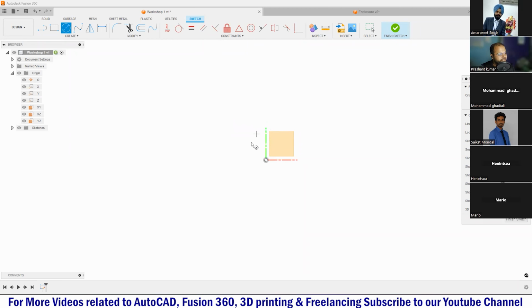So let's say I'm creating a circle. I will just select the center point of the circle and drag outside like this. Whenever I am dragging, there is a dynamic box. You can see that inside this dynamic box, I can put my dimensions. Like if I want to keep the diameter for this circle as 50, I can just write 50 from my keyboard and press enter. And here you can see, the moment I pressed enter, a circle of 50 diameter got created, right? So this is my first sketch.